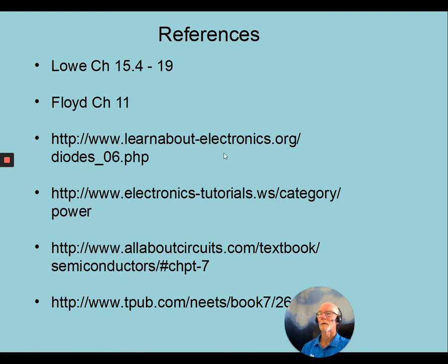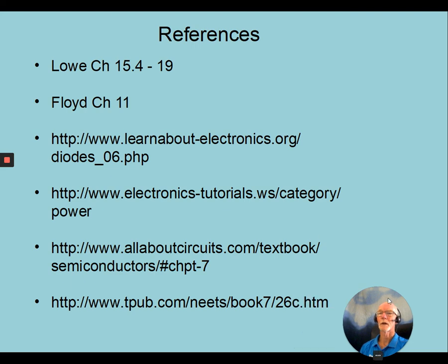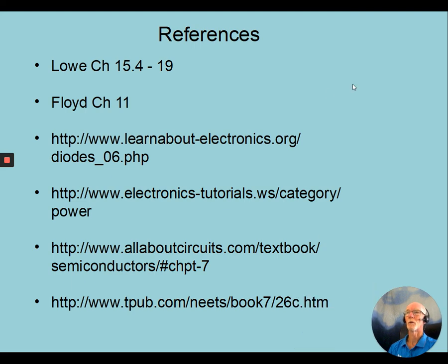So there's a lot of references to these circuits. We won't be investigating these circuits by themselves or building them, because especially the SCR and the diac require mains voltage, and we don't need to do that. But we will be investigating the SCR, and we'll see how it operates. It switches on, and then it waits until the current drops below its minimum hold on current and it'll turn off by itself, and then we've got to switch it on manually. All right, so that's switching circuits in a nutshell.